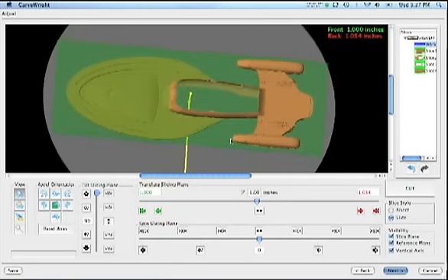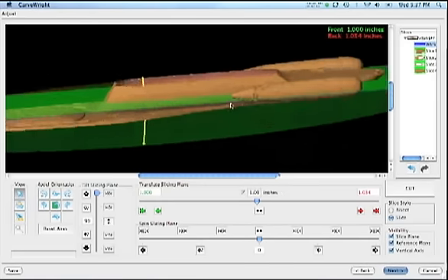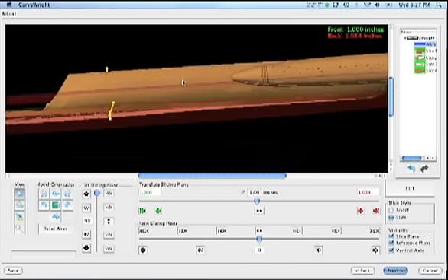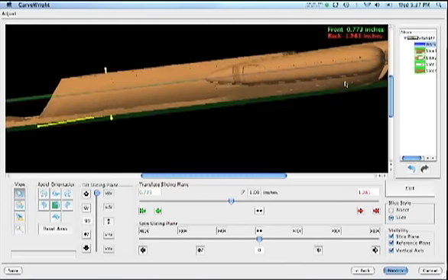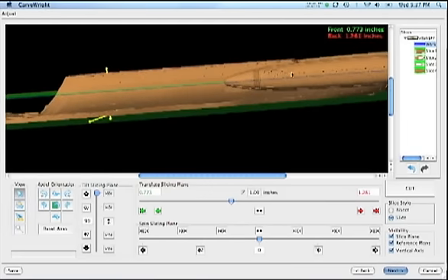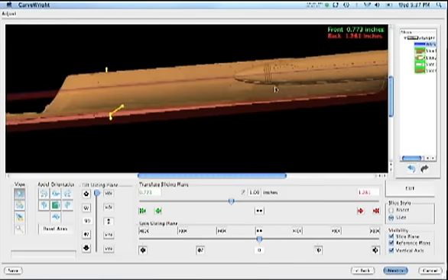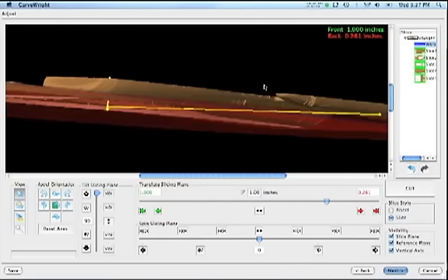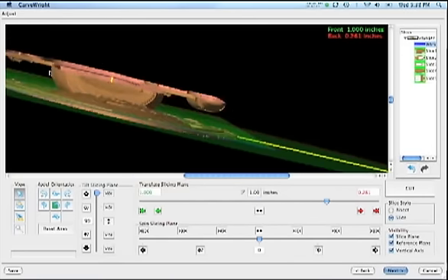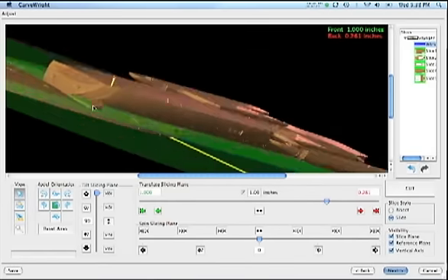And let's look at this. Now we've got 2 sides to these, so we can back off this 1 inch, kind of go right into the middle of these nacelles here, so that we got a good top and bottom cut on those. And let's cut that. And that also gets us to about the halfway point on this round area here, which is all going to need to be cut and shaped from the top.